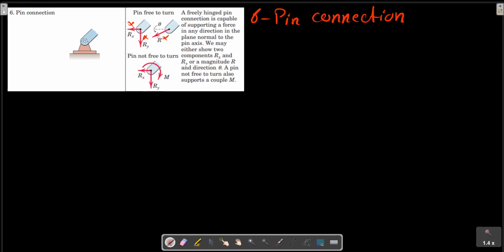The correct sense of this component in a specific problem depends on how the member is loaded. When not otherwise initially known, the sense is arbitrarily assigned and equilibrium equations are then written. If the solution of these equations yields a positive algebraic sign for the force component, the assigned sense is correct. A negative sign indicates that the sense is opposite to the initially assigned one.